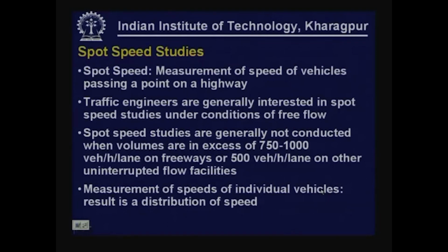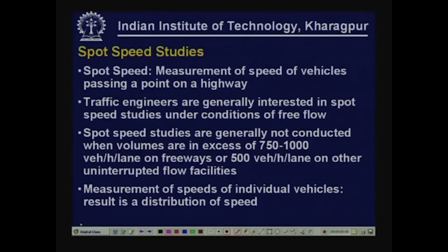Now, coming to spot speed studies. You know what spot speed is? It is a measurement of the speed of vehicles passing a point on a highway. It is a point measurement over a period of time. Now, remember that traffic engineers are generally interested in spot speed studies under conditions of free flow, because that is where we can use the spot speed data.